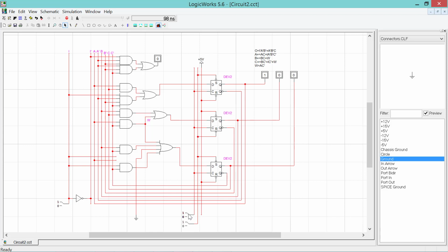Next we should go to state 011. 011. This is correct. Next we go to state 010. We maintain our output 0 because the alarm is not going off. 010. Let us clock again. 001. And now we should see an alarm.